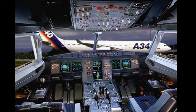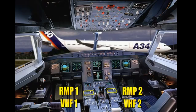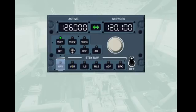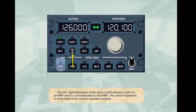On the A320, any RMP can tune any communication radio, but each one is normally dedicated to a particular radio. RMP1 to VHF1, RMP2 to VHF2, RMP3 to VHF3 or HF1. The selector light illuminates white when a pilot selects a radio on an RMP which is not dedicated to that RMP. This will be explained in more detail in the normal operation module.